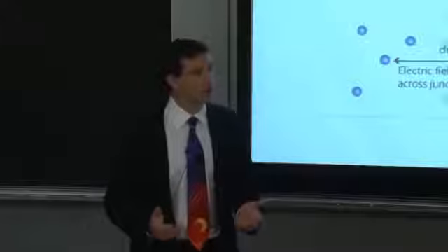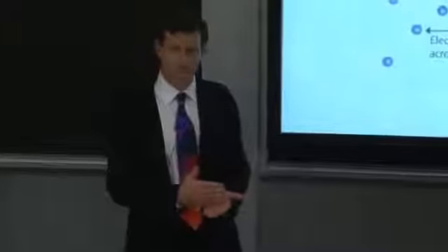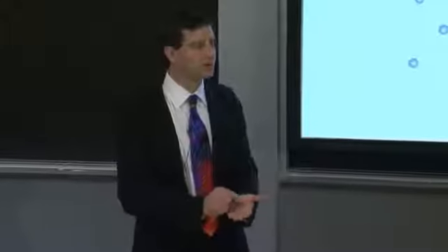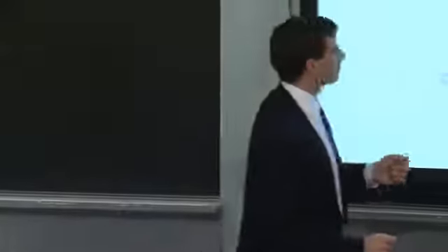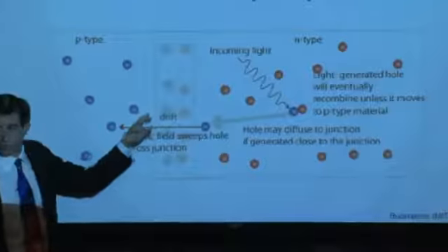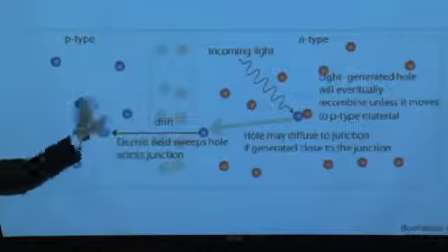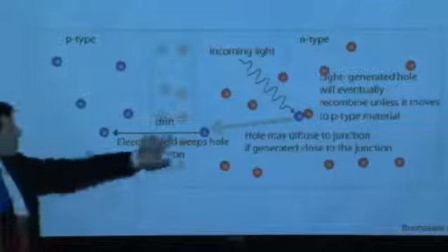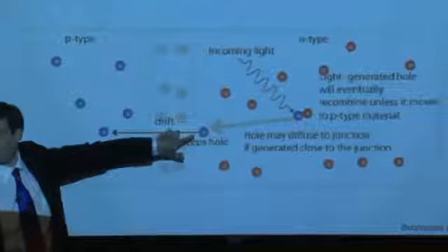And if you're ever in doubt, you can begin thinking about the process in terms of delta t's, small increments of time, where you imagine light coming in, generating an electron hole pair. Imagine that carrier moves to the junction, then moves across the junction. And then what happens? Does it immediately get collected? Does it stay there? What happens next? Is there an attractive potential between the carriers on either side of that junction? Asking those sorts of questions can help you walk through and troubleshoot what exactly is going wrong with your device.